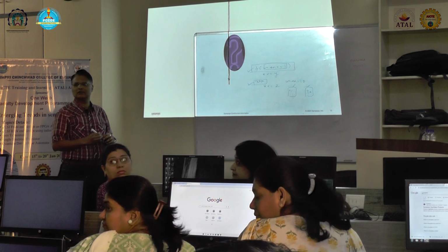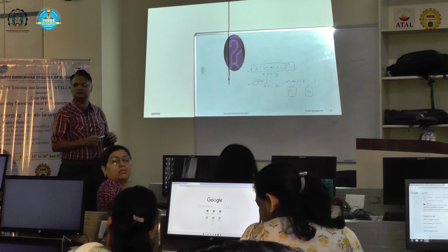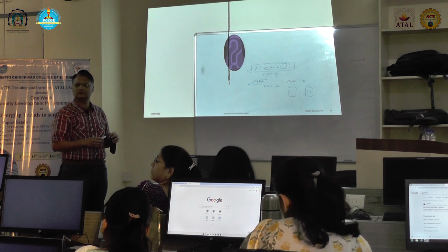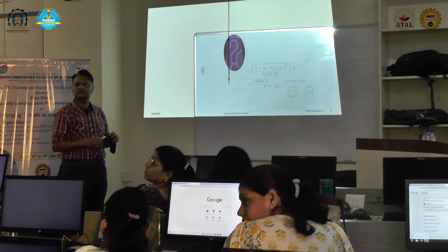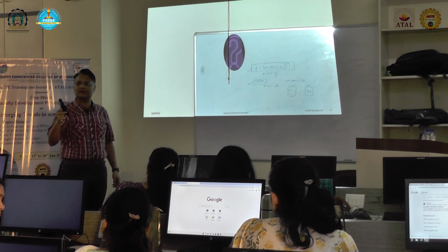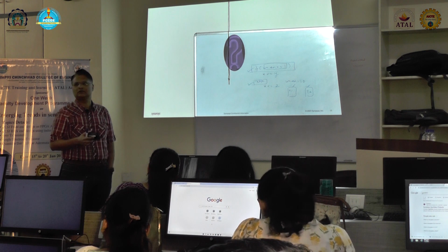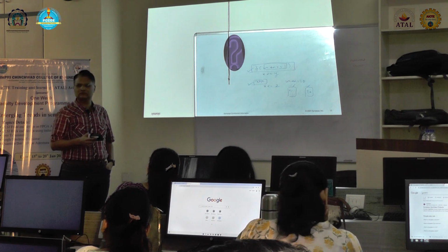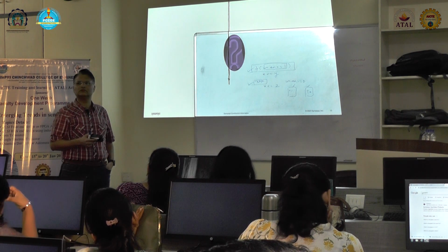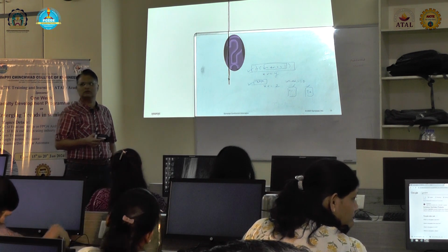Let's say there is a block which has some functionality based on a specific feature, containing multiple expressions or multiple features in a single block. That explains it, but block coverage is a very minute use. Usually we check expression coverage and toggle coverage. But it is part of code coverage itself. If you have defined modules which have block names and you want to cover those particular blocks, in that case you can have separate flags which will enable block coverage for that specific block. So it is part of code coverage itself.